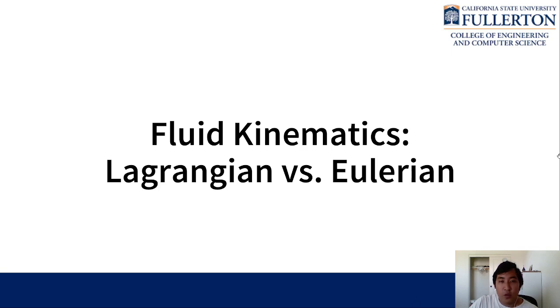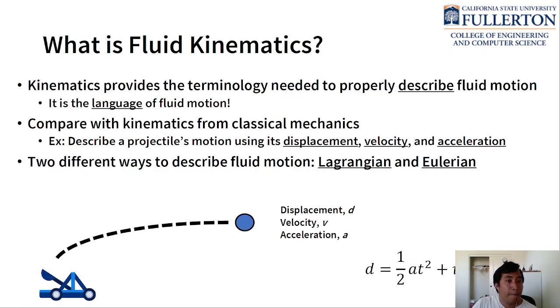Alright, so in this video we're going to review fluid kinematics, specifically the difference between Lagrangian and Eulerian descriptions of fluid flow. Okay, so first let's ask, what is fluid kinematics? Kinematics is probably a term you're familiar with, but basically kinematics provides us the terminology needed to properly describe motion. The way I like to think about it is it's the language of motion.